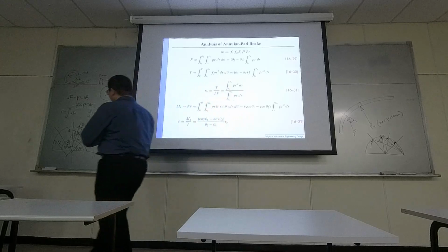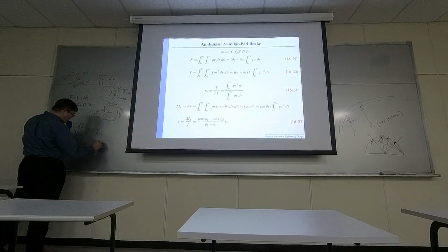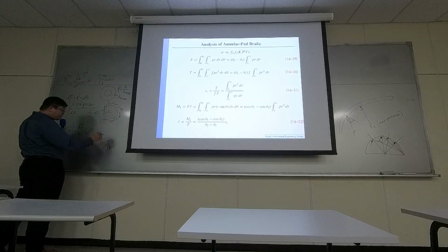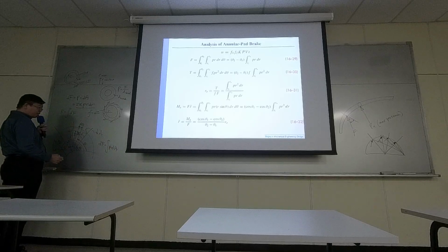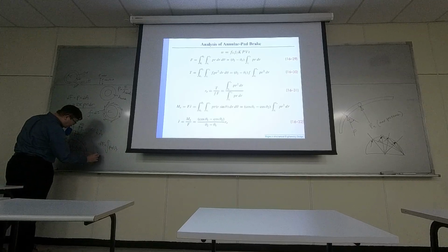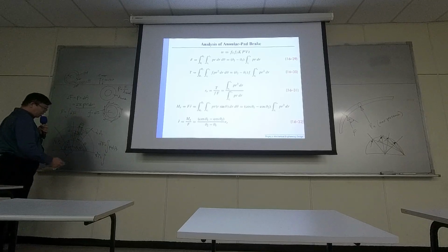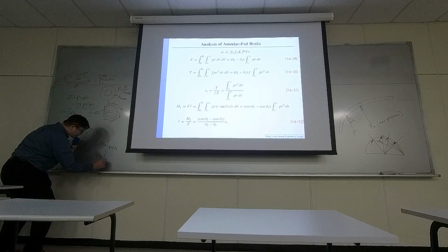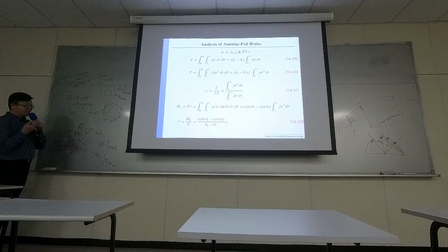Same idea. So dF equals the pressure at that particular point times dA, right? And the torque, dT, equals the friction coefficient times dF times R.